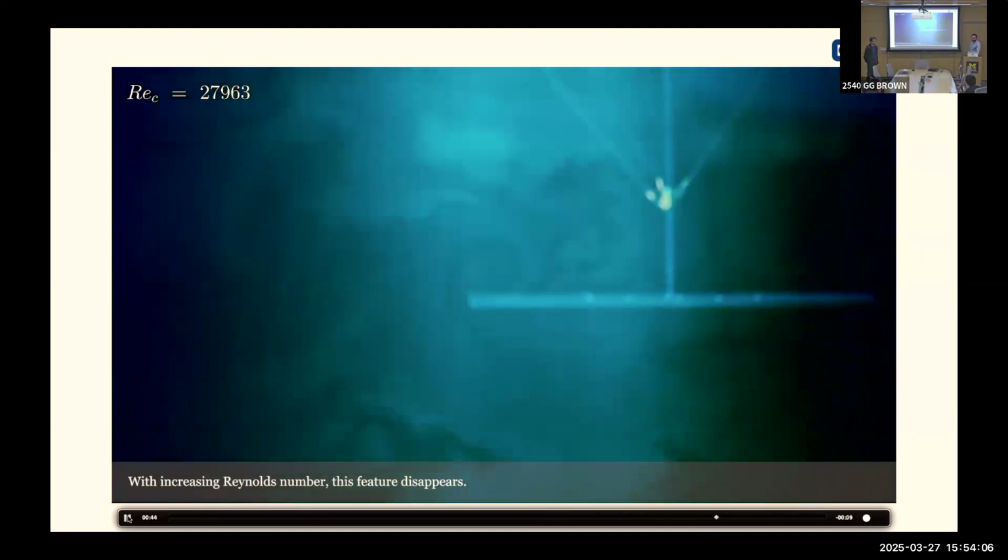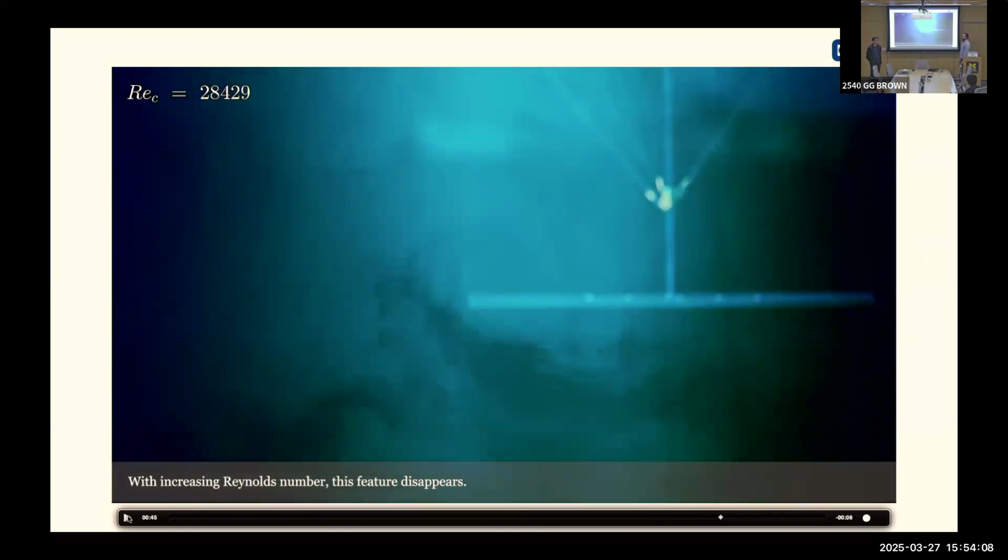Is your smoke injected downstream of the honeycomb? So this video I mostly show because it's nice to look at, right? Functionally, the way the wind tunnel is, it's recirculating. Our main smoke injection is downstream of the test section, and then it gets entrained into the fan, and goes around the loop, and then comes back into the test section. That's also why in this video it seems intermittent where the smoke is, because we see the test section and we're starting to film the whole time.